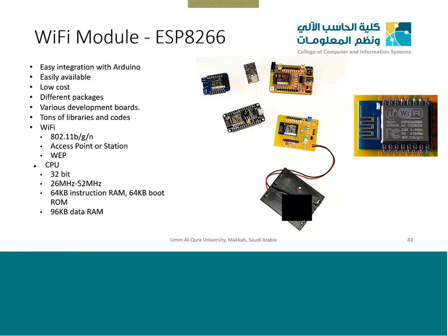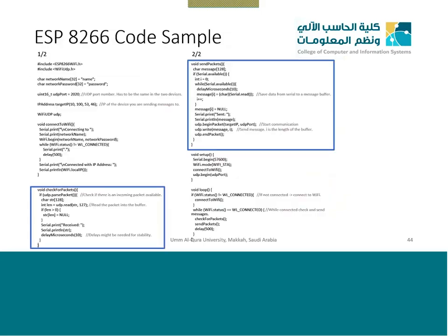We connect this with Arduino, like the temperature sensor application I told you about. Arduino sends the data to the server, and it can also receive data from the server. Maybe Arduino has, for example, a relay connected. Based on the input from the server, it can turn that relay on or off.